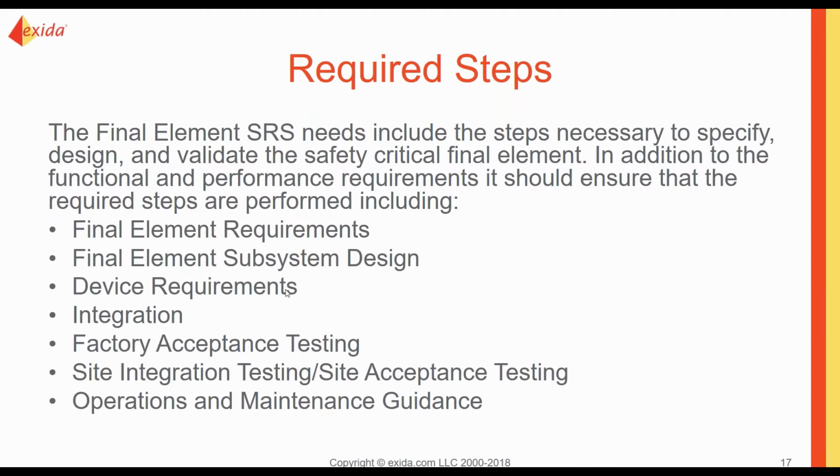Now, these things are well covered in 61508. So if you've got a certified actuator or a valve, you should have the information at this device level. But not everything you put into a system is going to be certified, and that's where this second bullet of the subsystem design comes in. We're going to have integration of the final element, factory acceptance testing, site acceptance testing, so inside integration and acceptance testing, and then ultimately operations and maintenance guidance.